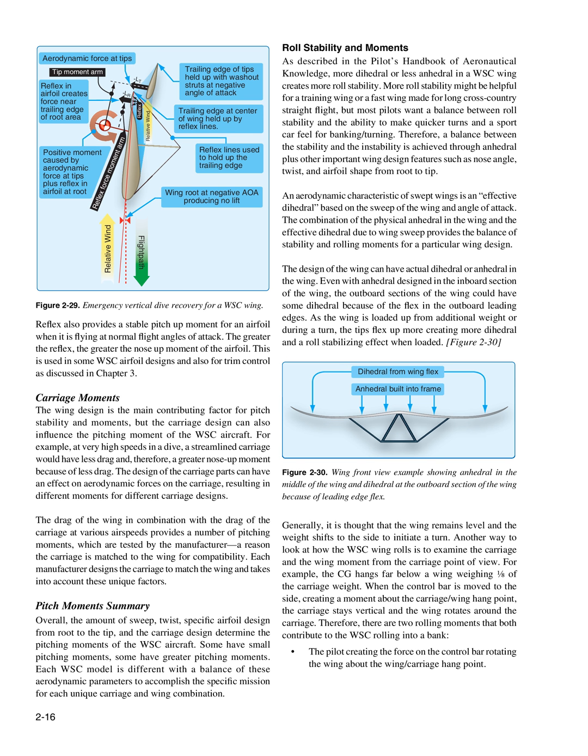The design of the carriage parts can have an effect on aerodynamic forces on the carriage, resulting in different moments for different carriage designs. The drag of the wing in combination with the drag of the carriage at various airspeeds provides a number of pitching moments, which are tested by the manufacturer, a reason the carriage is matched to the wing for compatibility. Each manufacturer designs the carriage to match the wing and takes into account these unique factors.